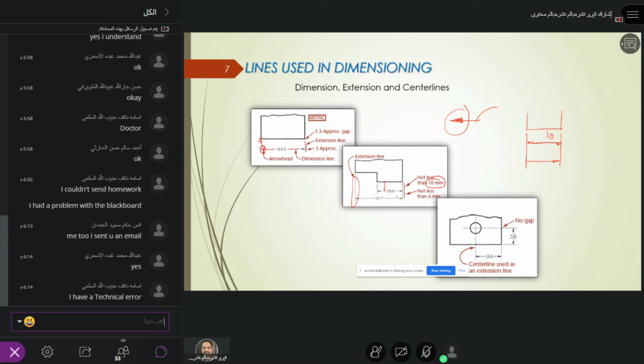And from one dimension to the other dimension, it should be like 6 millimeters. So let's say this is your object. The first thing I do is the bigger one. Normally I will draw it here. So this is my object. First I draw the dimension extension line here. We should not touch it, and I extend it here as well. Then the first dimension should be 10 mm, so I will draw from here.